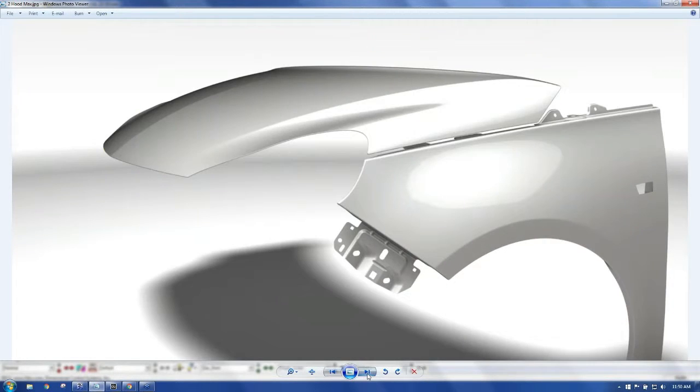So then what I do is I will color each spec study initially a specific color. So here I have a nominal hood in yellow, and my fender might be in a deviated position. So all of my nominal geometry, I have a variant set that says, okay, paint all nominal geometry yellow. It just makes the workflow for me much quicker to be able to build my variants, know what parts are associated with what spec study.